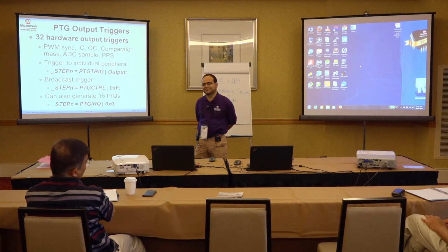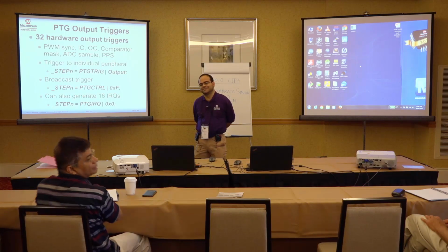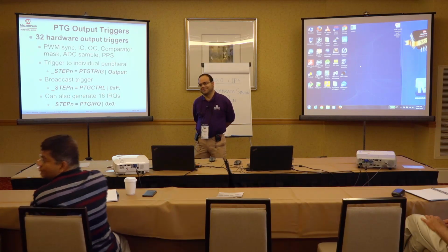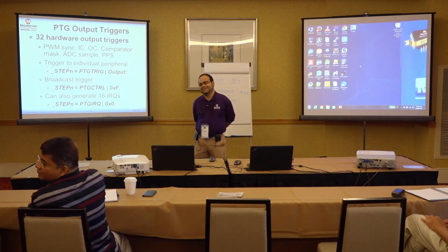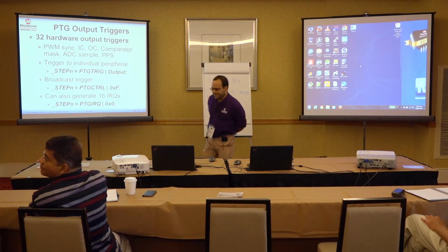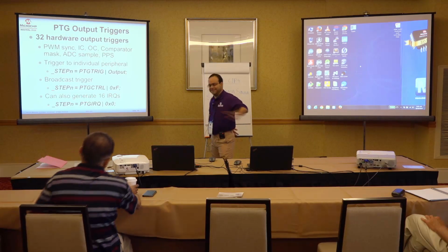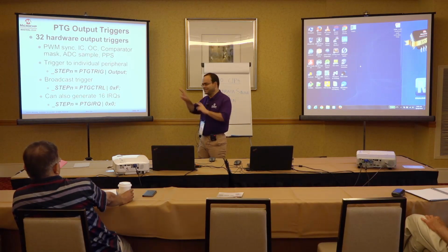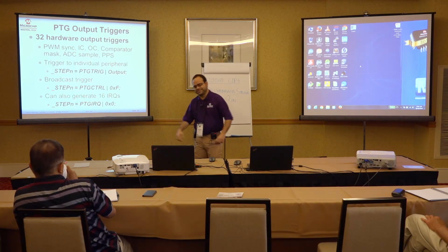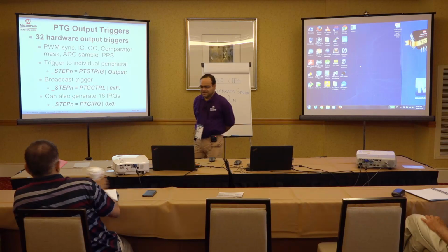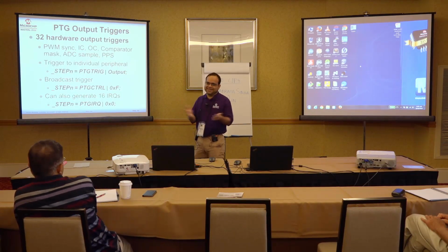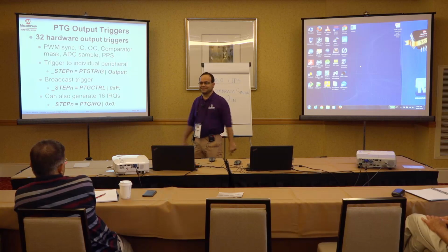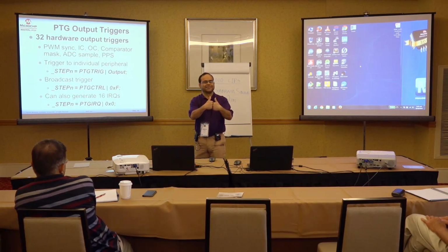Or you could possibly use the CLC, just look at multiple inputs and find out which event happened. You don't have very many instruction steps, but it's a possibility. The only problem is that the devices that are currently released do not have both CLC and PTG together. So PTG does not have a hardware input trigger from the CLC on the existing devices. Newer ones might. As we have devices with PTG and CLC together, then there would be triggers. So the CLC can be used to combine those multiple peripheral events, maybe with a logical OR.